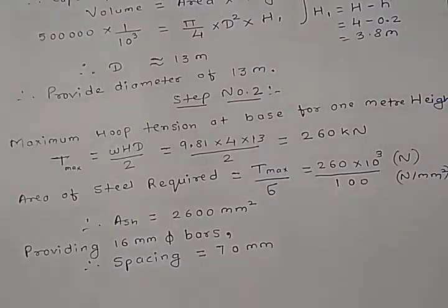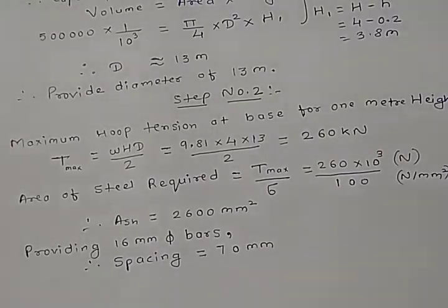So this is coming out to be 70 mm, and you can provide this 16 mm diameter bar at a spacing of 70 mm.